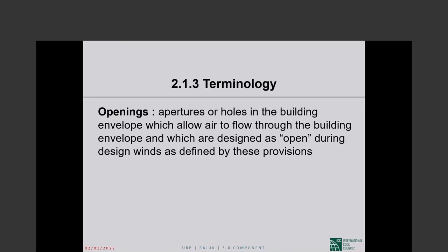You take a hangar or an automobile repair shop, those roll down doors, those are huge openings. If they're treated as openings, it can change the enclosure classification of the building. Are they openings? Are they enclosures? So you have to treat them as openings unless there is a crew in place and instructions in place to make sure that a roll down door will in fact be closed at the approach of a storm. Okay, otherwise they're openings.